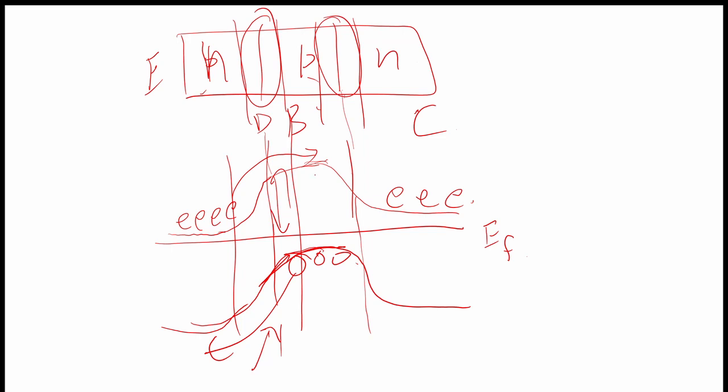Now if we somehow reduce this barrier height, the electrons can flow from the emitter side to the collector side. So from the base terminal we can reduce the height and flow the electrons from the emitter to the collector through the base. So the current will be decided from the base junction.